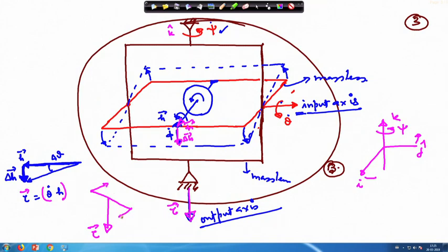So, this is equivalent to a force applied like this in the horizontal plane. Okay. So, this is the force applied in the horizontal plane, means it will cause this external gimbal, or the outer gimbal, to precess. Okay. And so how the satellite will then be controlled, how you can change its orientation, that is the question.